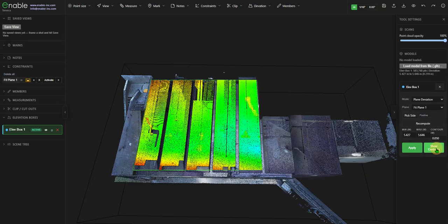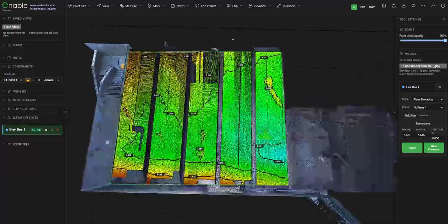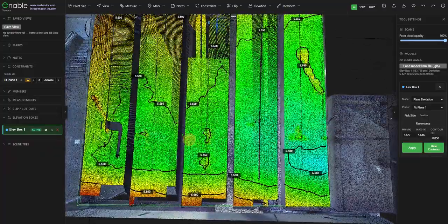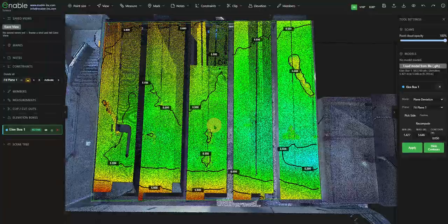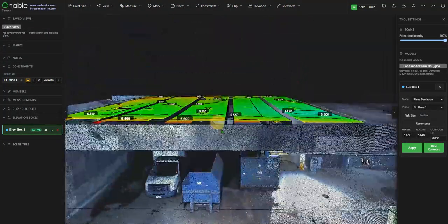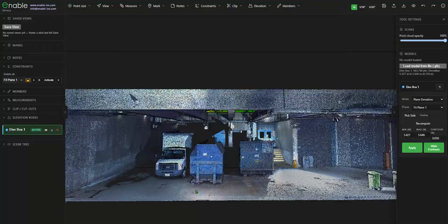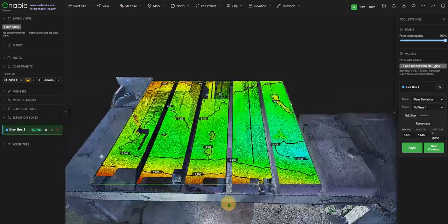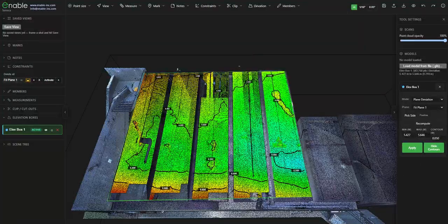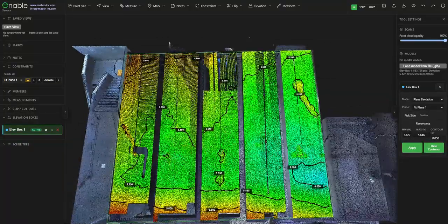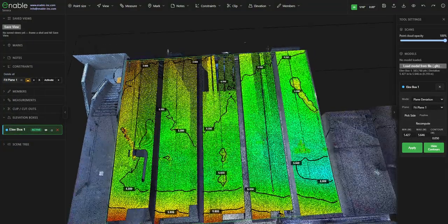If we want to see those contours, we can do that. And you'll notice that these contours are fairly consistent in this particular example, unlike the previous one. And that more or less makes sense because the plane that I'm fitting to, or finding the deviation from, I should say, is relatively consistent, this slab on grade. And as long as there weren't too many issues with the formwork, the underside of this slab should be fairly consistent. And that's good for props and the like. We don't have, say, a much larger distance over here compared to this bay over here.